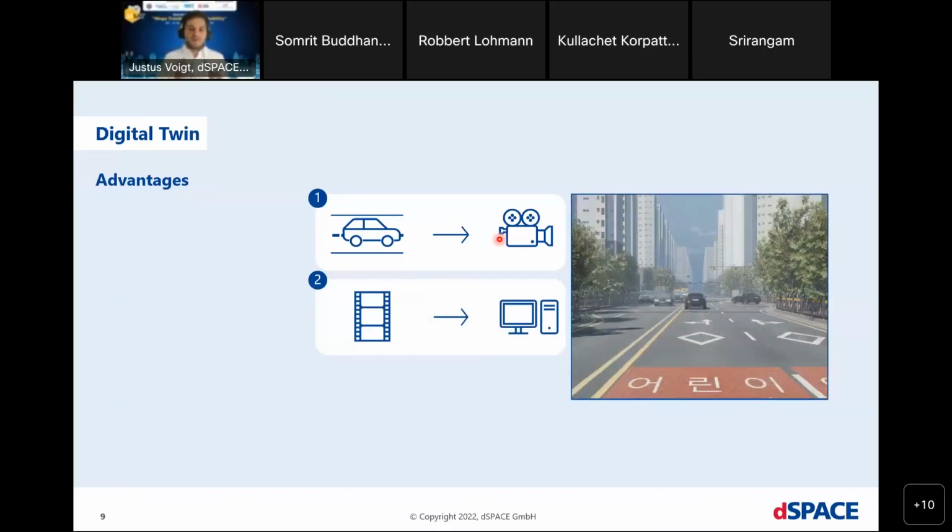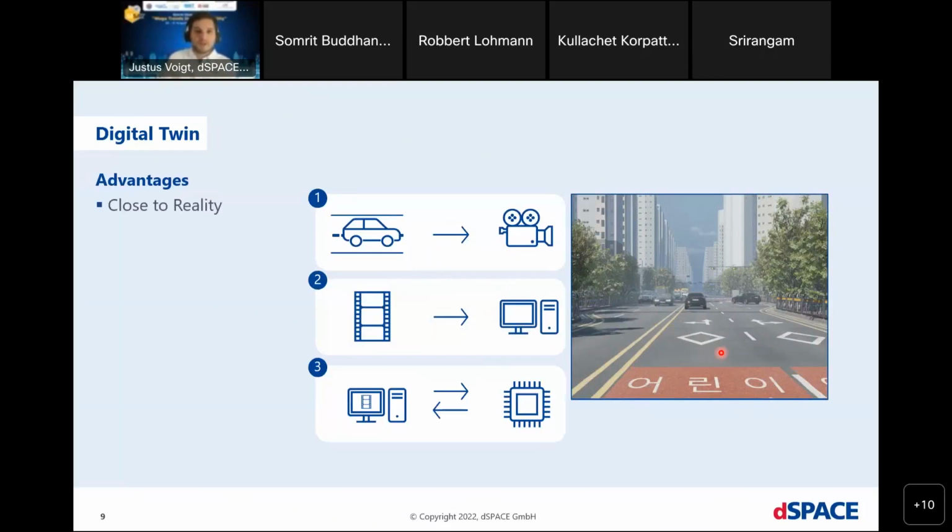So I have a model of the vehicle, the fellow vehicles, pedestrians, the sensors, and the environment. Of course, afterwards, I have all degrees of freedom to modify any behavior since this is now a simulation. And with good models, the data quality is still close to reality. Tests can be performed both as closed-loop and open-loop tests, and even critical driving maneuvers are still completely safe. The simulation is deterministic, and of course, we can vary every parameter.